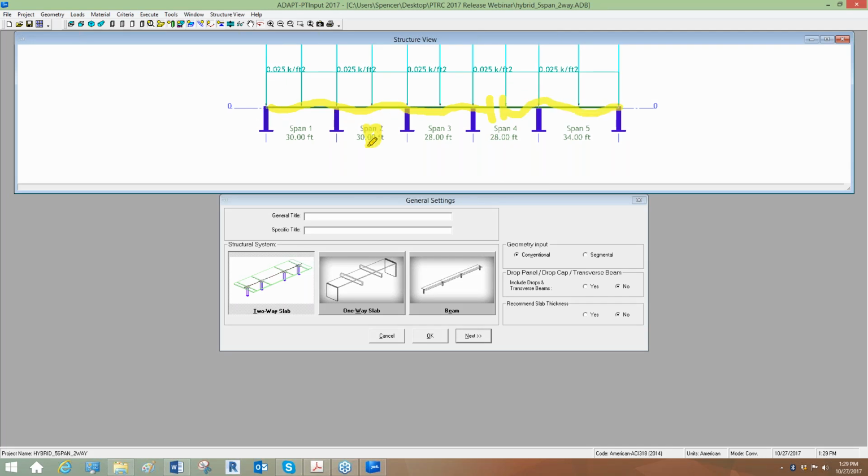This is going to be tendon B, and this is going to be tendon C. Tendon A is always present in our model. So tendon A always goes from start over here to end. So the only way to avoid tendon A actually being used is to simply set its force to 0. So that's what we're going to do in this case.